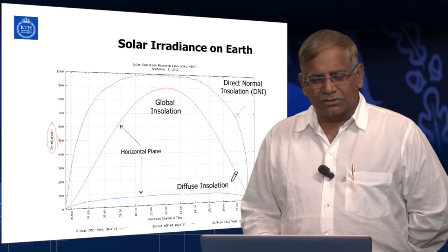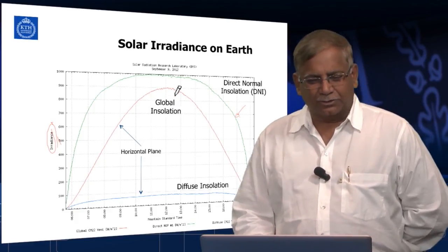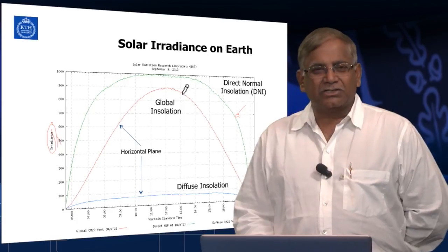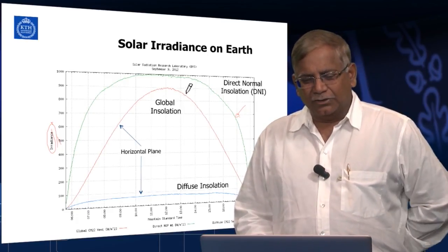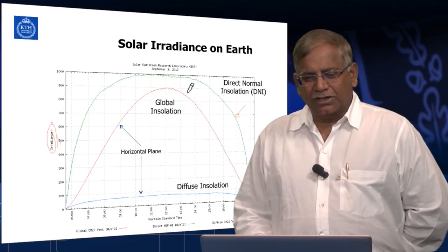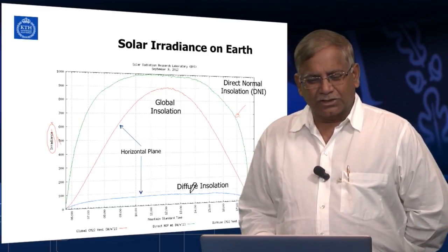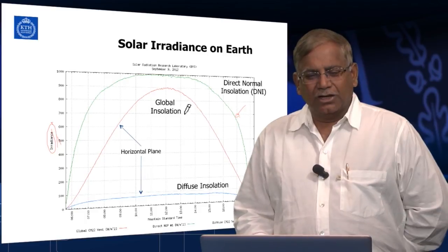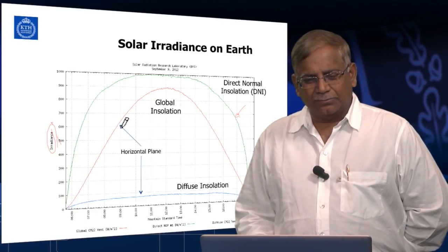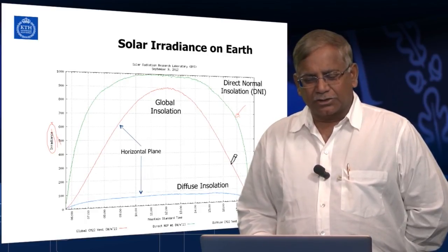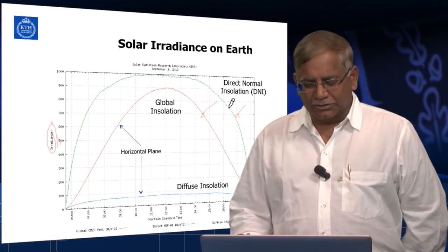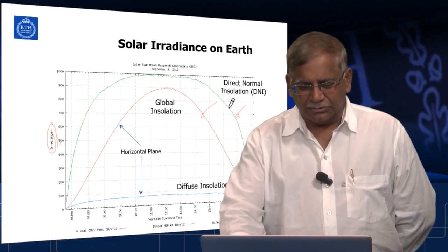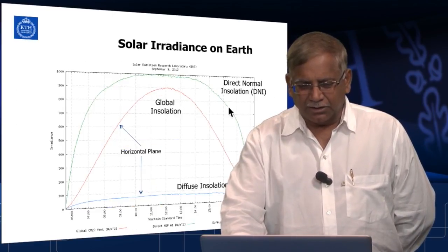But in the rest of the country, for example in Florida, although it is called the sunny state, most of the time the humidity is very high, and you have water droplets in the atmosphere. As a result, you get a lot of diffuse radiation, and hence the typical insolation which you see during the day looks more like this curve as opposed to this curve.